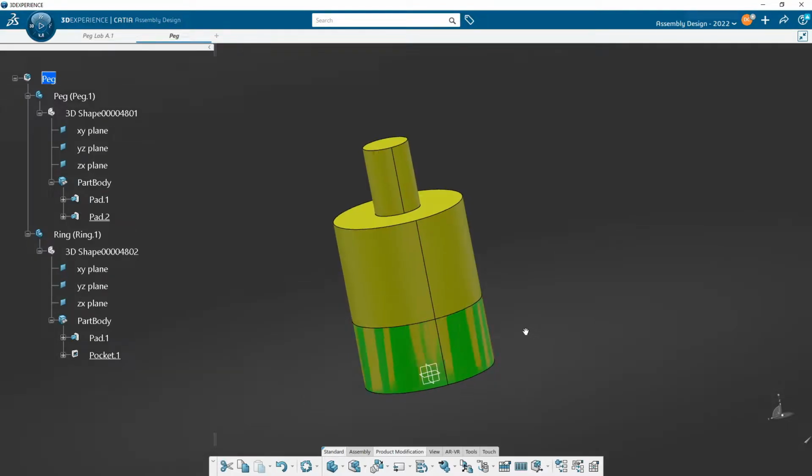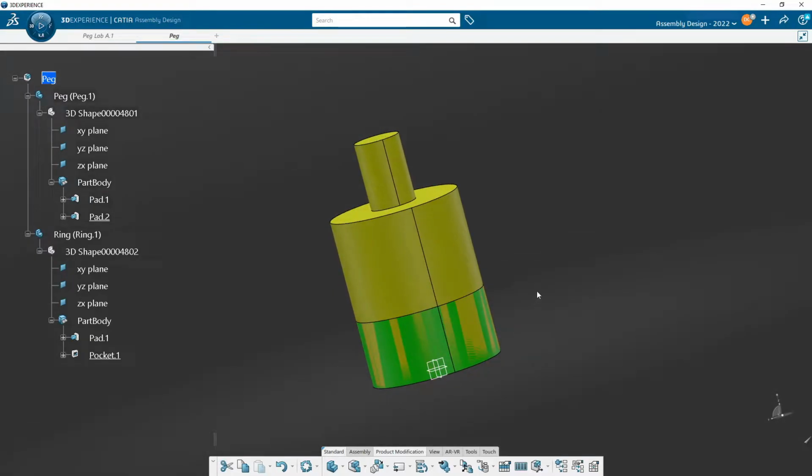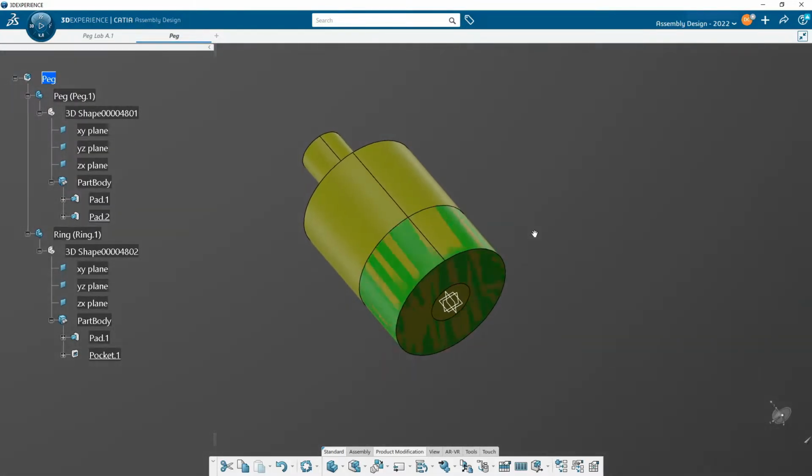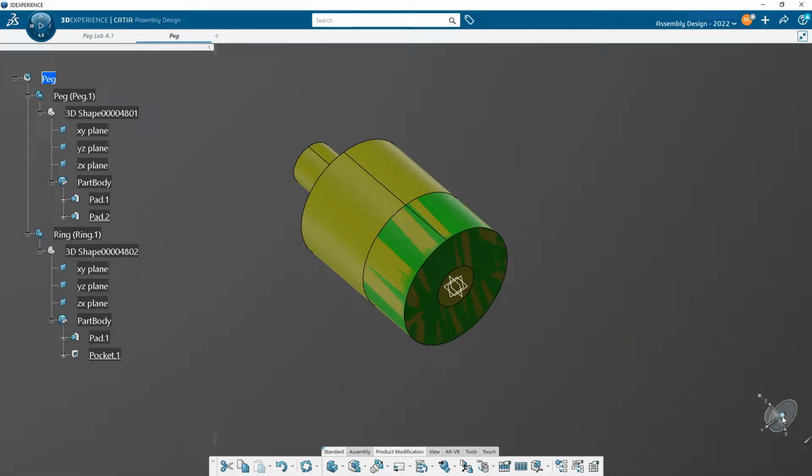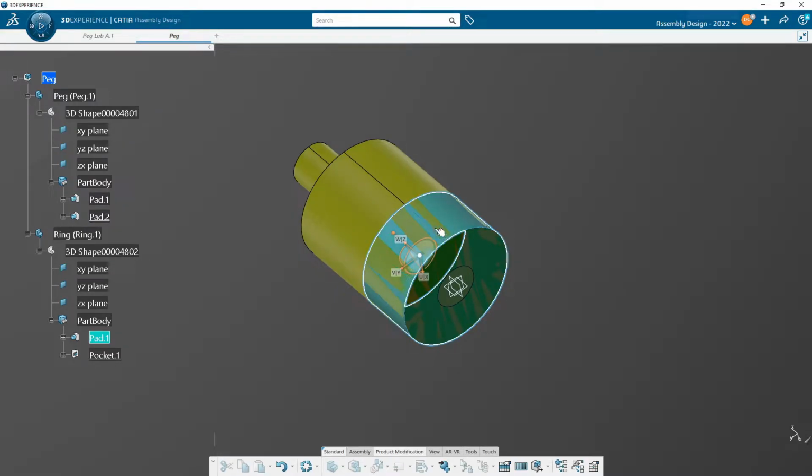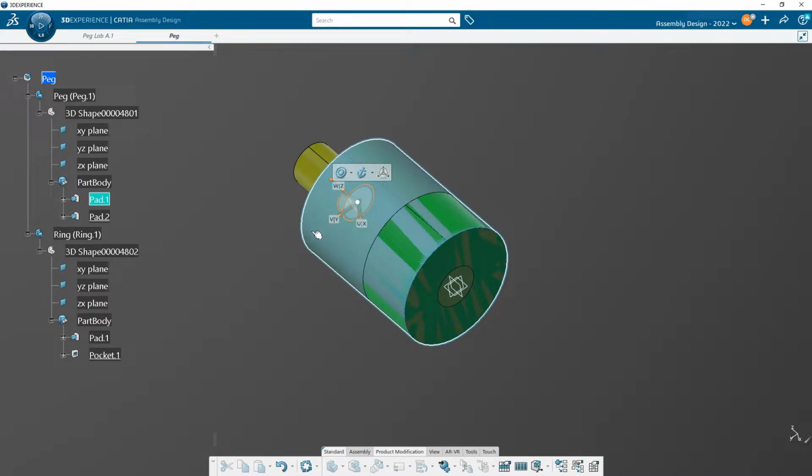Now the other thing I might want to do is possibly move this around a little bit. So if we recall, we can take our compass down here and I can stick it to things. I could stick it to this. Now notice that when I stuck it to it, it highlighted the ring portion of this, but it really easily could have possibly got stuck to the yellow instead. So be mindful of what thing it's sticking to, okay?